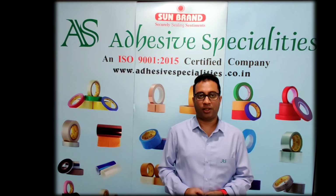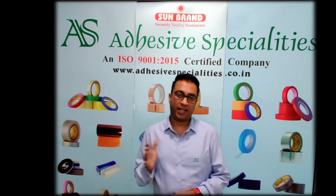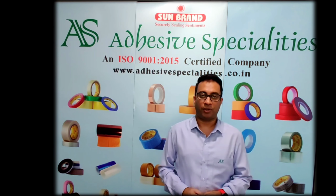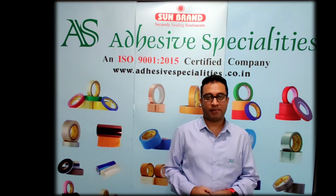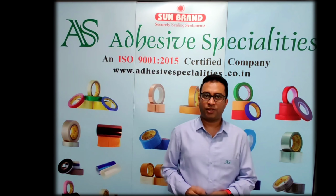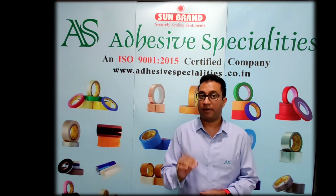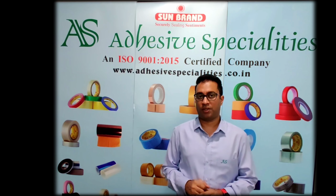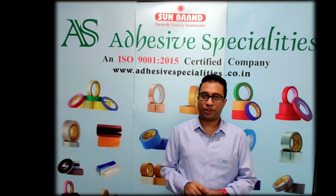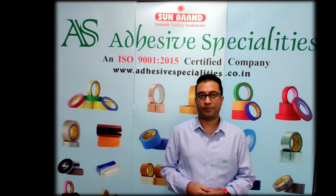Peel adhesion. Peel adhesion is the strength of the bond between the tape and the surface it is applied to. The industry standard is ASTM D1000. Adhesion to steel. Poor adhesion can result in a failure in electrical insulation, therefore it is imperative that the right adhesive is used. Acrylics provide the best adhesion, after which come rubber and silicone adhesives.